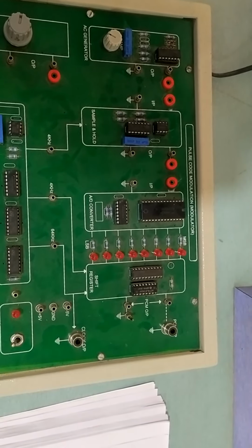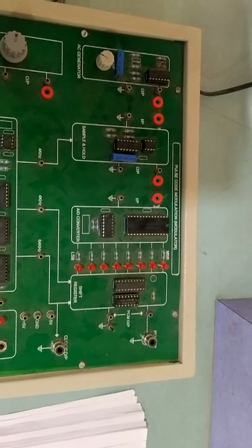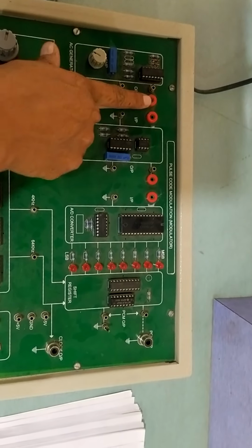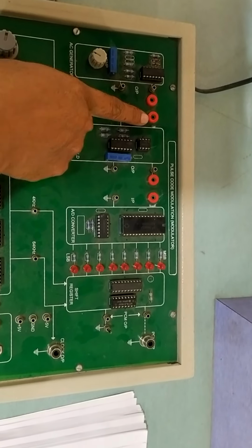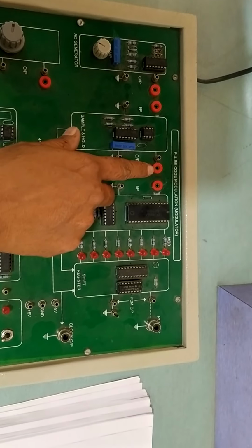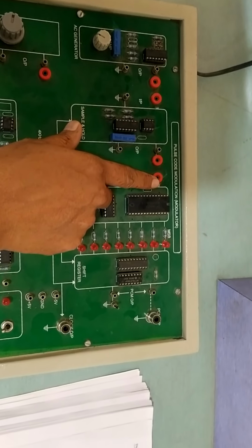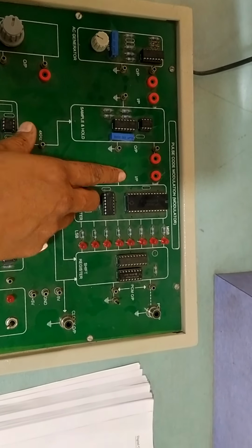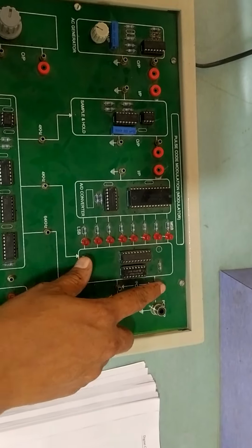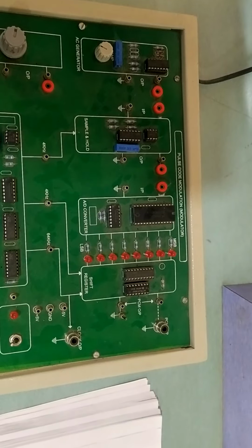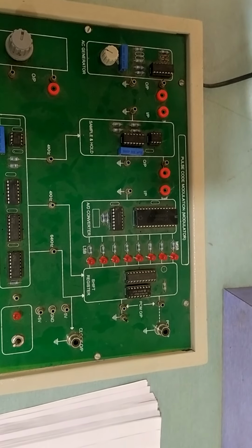Now we can make the connections. We have to connect the analog signal output to the input of the sample and hold circuit. Here the grounds have to be connected. After that, the output of the sample and hold circuit is applied to the analog to digital converter, and here the grounds are also connected to each other, and at the output we get the PCM output. Now we can make the connections, and one by one we will see the signals or waveforms on the CRO.